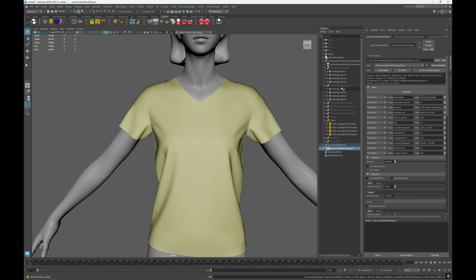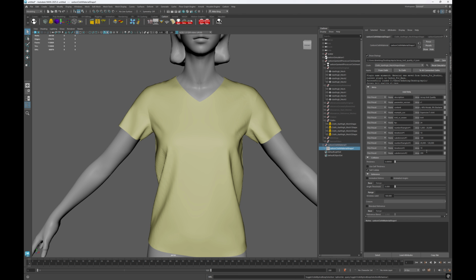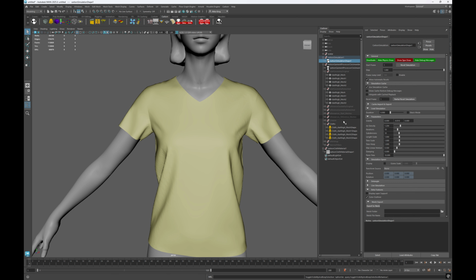Now here we have about 31,000 triangles, and so 200 is probably too excessive because it's not that much more than 20,000. I think I would start with 10 and 100, and let's just see how that behavior is. So to do that, we go into the carbon simulation and we set iterations at 10 and subdivisions at 100.